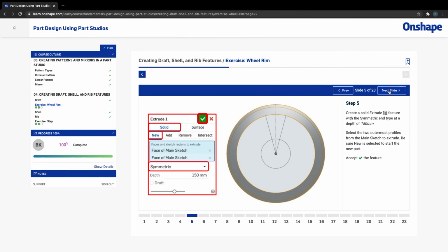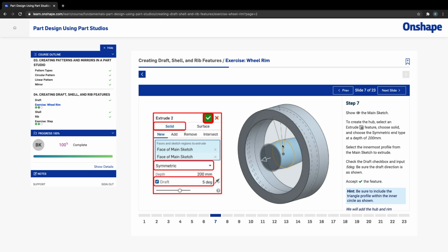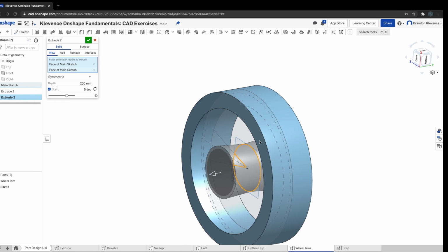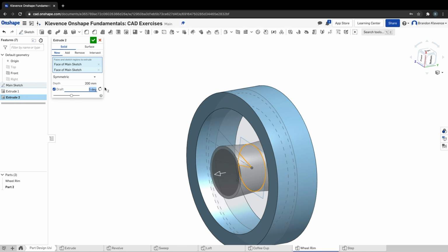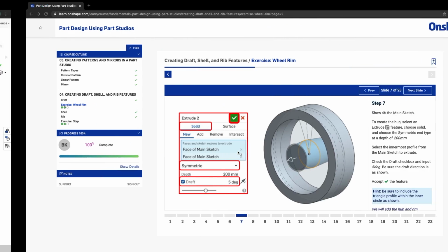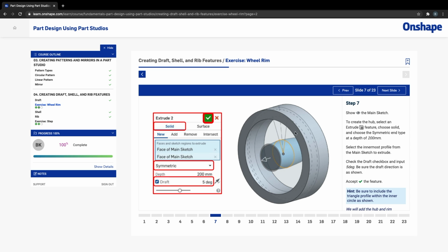We don't want it to be like an hourglass shape. If we look at the tutorial here, we want it to be like if we stack 2 cups open side towards each other, we want the angle to be going outwards. So we don't want that hourglass shape. In order to change that, we can hit this opposite direction arrow here, and then we'll get that. So now you can see how it looks pretty much like the tutorial.